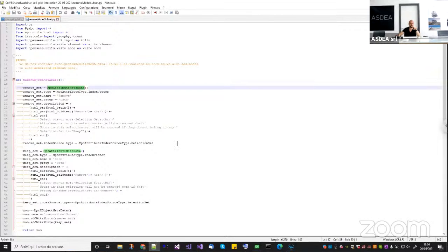Actually, they do not have to have the same coordinates, but it is better if they do not share the same Z coordinate, because if they do, you have some round-off errors, and sometimes some node may not be in contact with the beam. Okay, so let me explain this point a little bit. Thank you for reminding me.